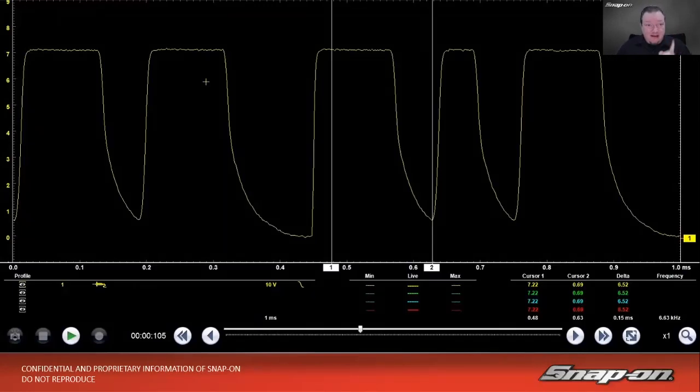So what this indicates, and this can be useful for many different signals, is that if it's a signal that pulls down to ground, and it looks like this, where it kind of curves when it's pulling down to ground, that means it's taking a very long time to get to ground, because a scope is a value over time, right? So this one actually made it to ground. This one never made it at all because it was too short of a pause between here. So it's coming down and it's just not making it to ground. So that is a problem on the ground side. It's not able to pull it down fast enough to ground. So that is an issue.